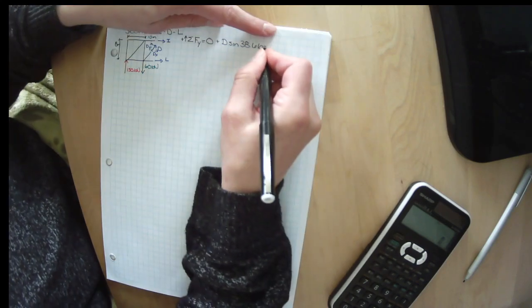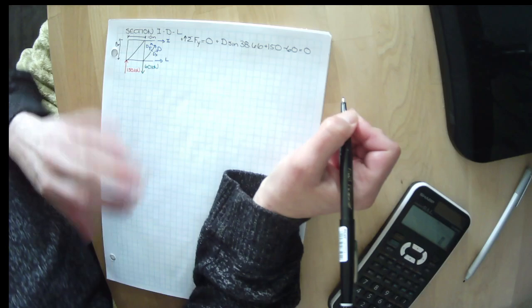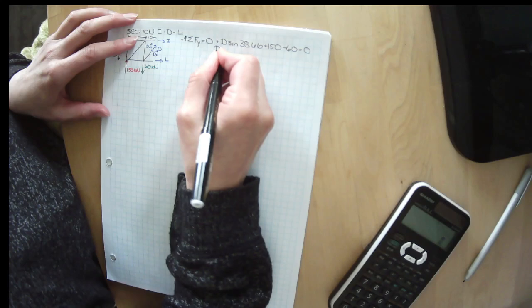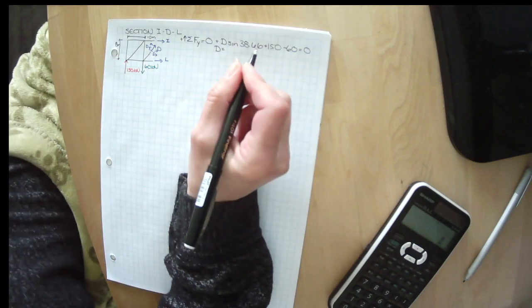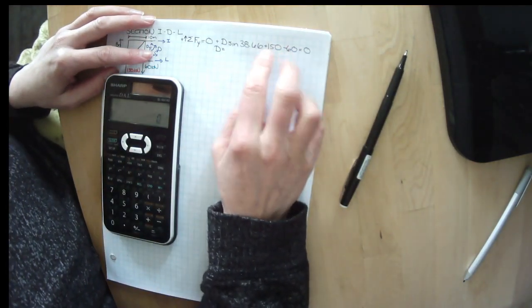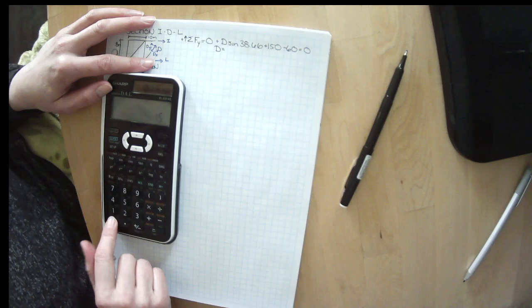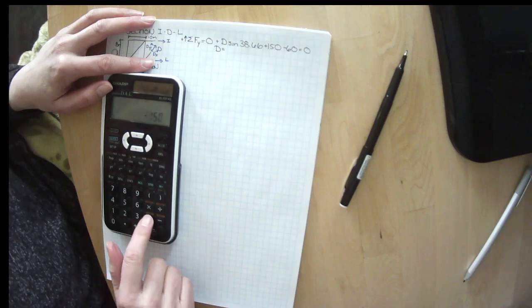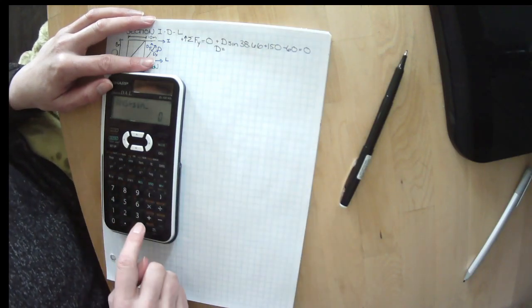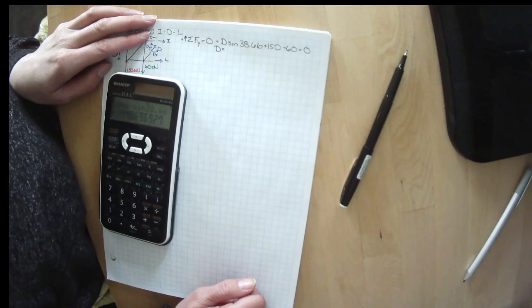We've got 150 kilonewtons going upwards, and we've got 60 kilonewtons going downwards. Those are the only things acting in the y direction. We can solve for d. We can bring our 150 over and it becomes negative. We can bring our 60 over and it becomes positive. So we have negative 150 plus 60 divided by the sine of 38.66, and we get that d equals